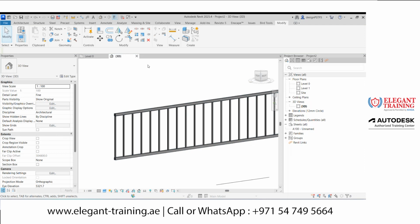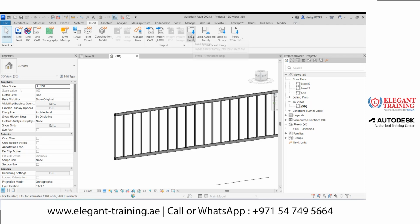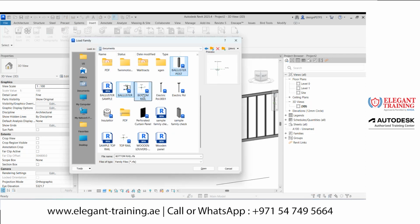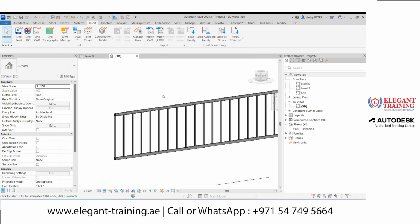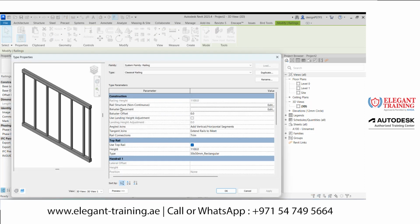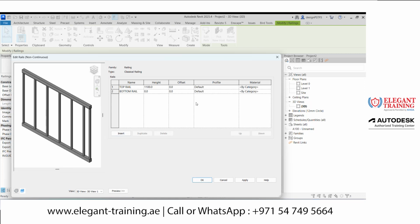So we need to load all these families we had created. I can go to Insert, then I can choose Load Family. These 4 families, I'm going to open them and load them in the project. And now let's go to the exact positions where you can change the profile. From there only you can select the loaded one. So I go to edit type. For the rail structure, I click edit here. I had already created top rail and bottom rail.